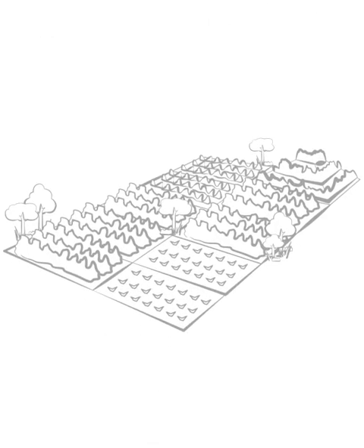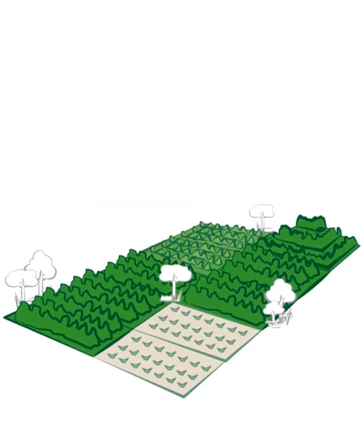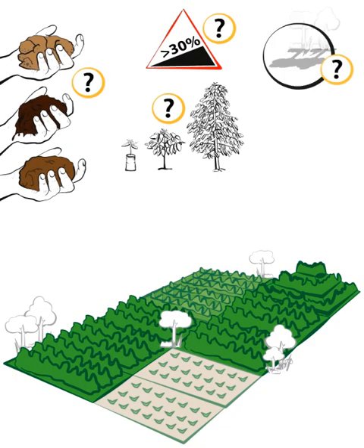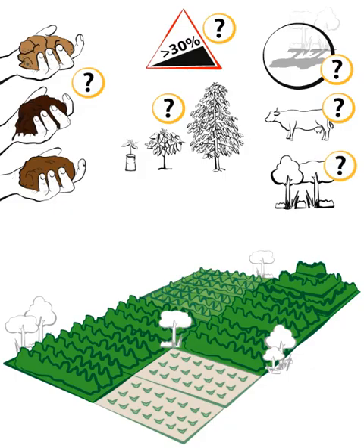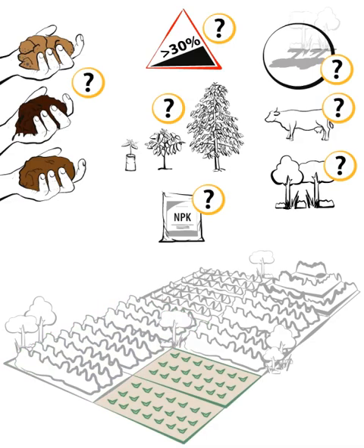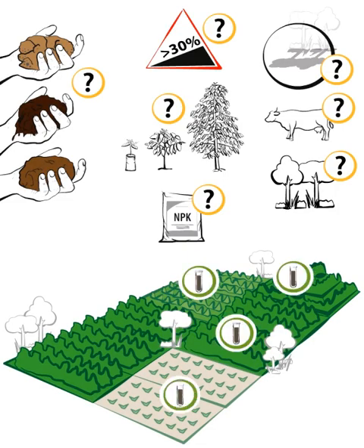Prepare the soil analysis as follows. Identify the field or plot for soil analysis. Divide the plot into sampling blocks based on soil type, slope, plant age, shade, land use history, vegetation, and fertilization practices. Each block should be as uniform as possible in terms of soil type, slope, management type, etc.